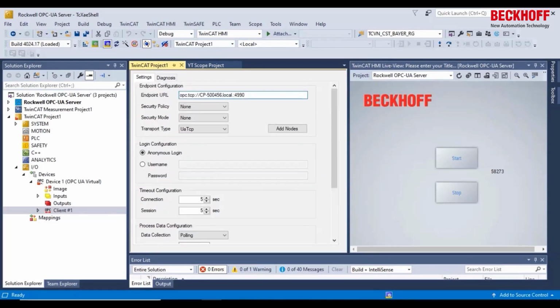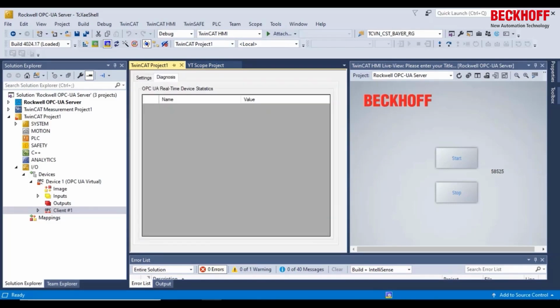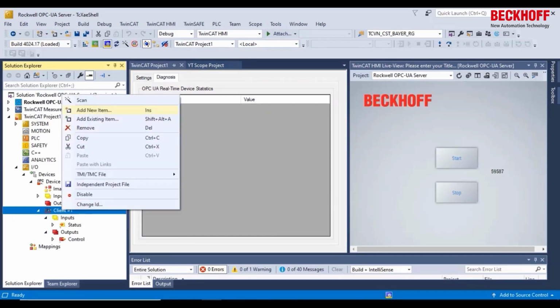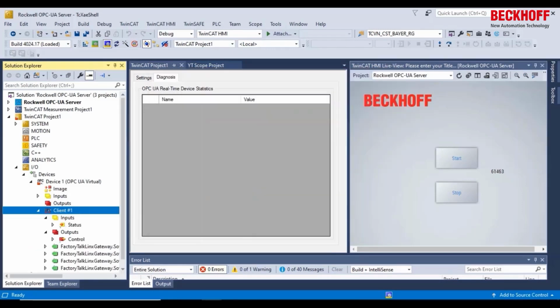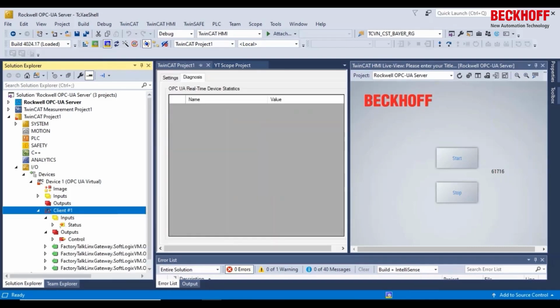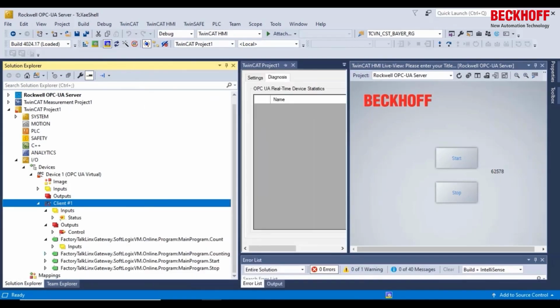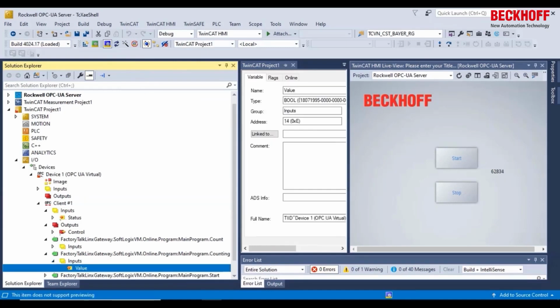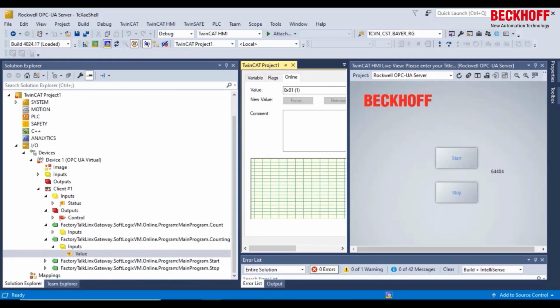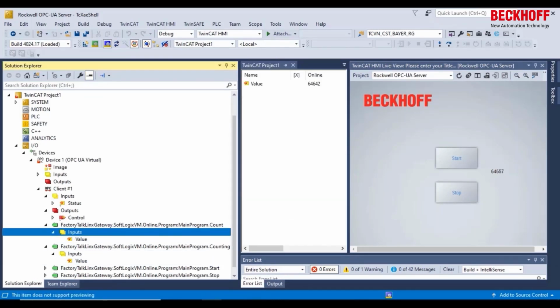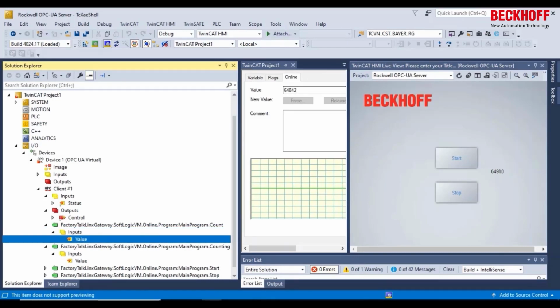Now down here under the data type names, I can give variables new naming. There's a diagnostics tab. But what I really want to do is just right click and hit scan. And scan's going to go out and ask the server, or the OPC server, what tags or what nodes, objects are available. And so I browse through here again. We see that here's all of my start stop bits, and we add those to the IO tree. We kind of look through those. So yes, we get values. We're going to be reading those. Some of these we'll enable here in a moment to write. We can see that if we just click on them right away, in the middle window, we get live values.